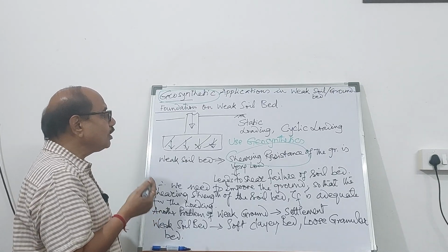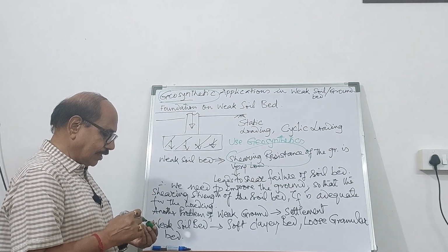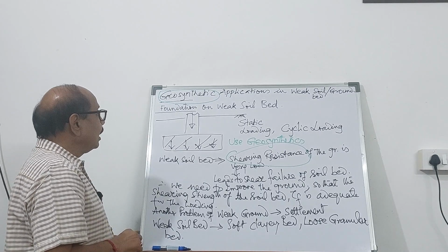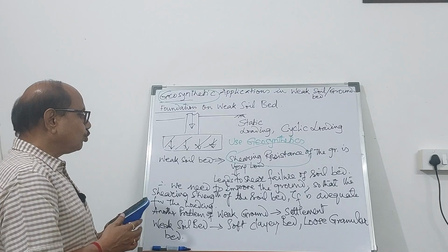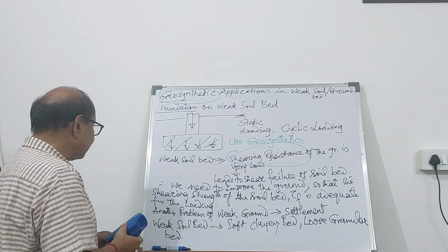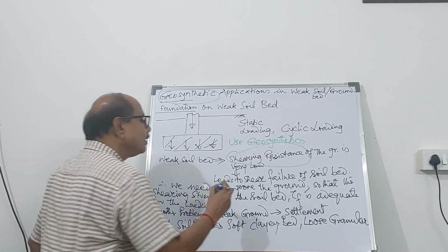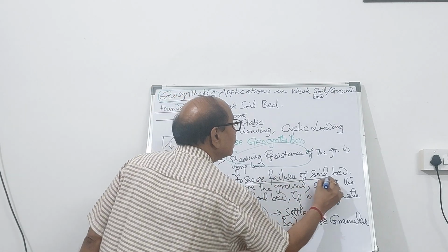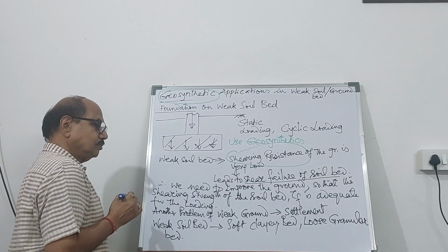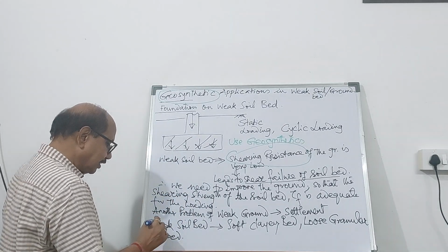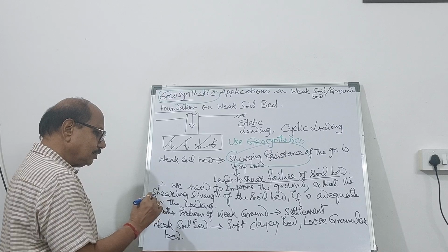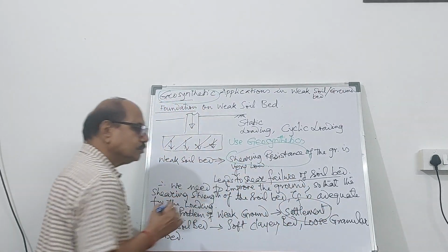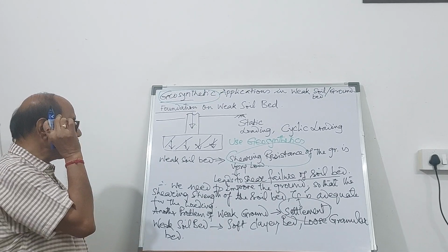So how to improve the load carrying capacity if I need to have a foundation? It should not fail in shear. There must not be any failure of the soil bed. And also the settlement aspect must be looked into. This is also important. No excessive settlement.